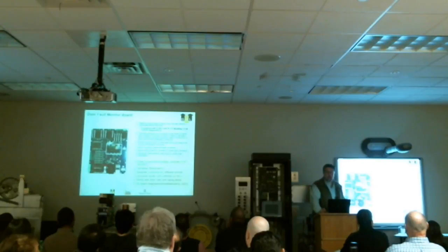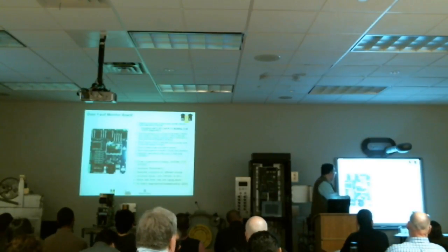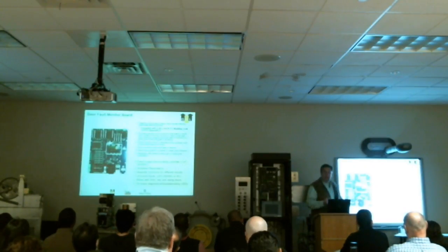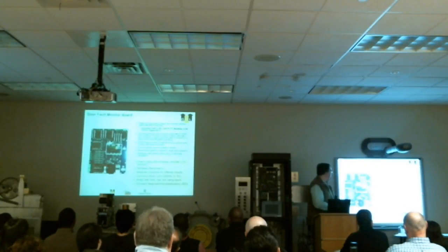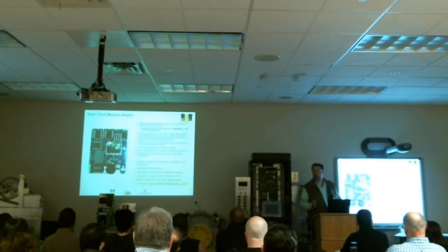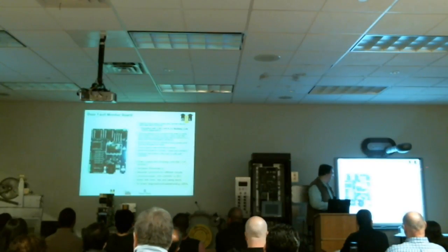All right, relay logic, solid state, PLC controller that's going to be out there on the market. Again, designed to meet the criteria, the code for door lock monitoring, as we had mentioned, okay, to be able to detect the status of the door's position, as well as the status of the door locks themselves, and obviously inhibit the elevator from running when any of those fault conditions occur. Now, this panel, we worked on it for quite some time. We try to keep it as generic as possible, because obviously the controllers that are out there are vast in nature in terms of the different types of control products that you can run into.